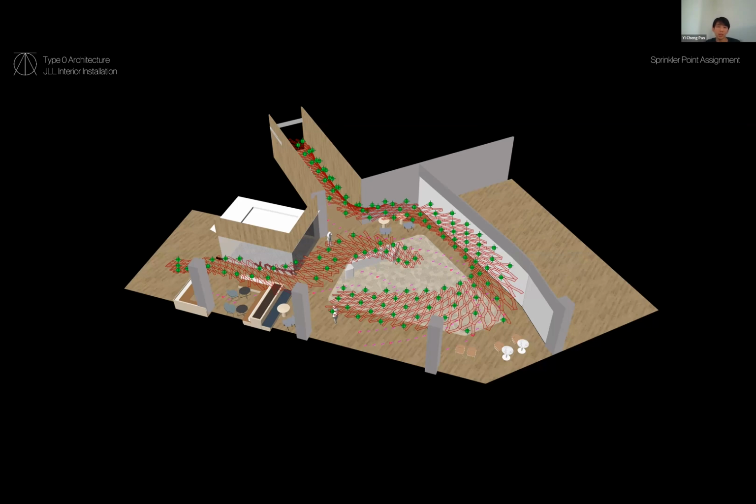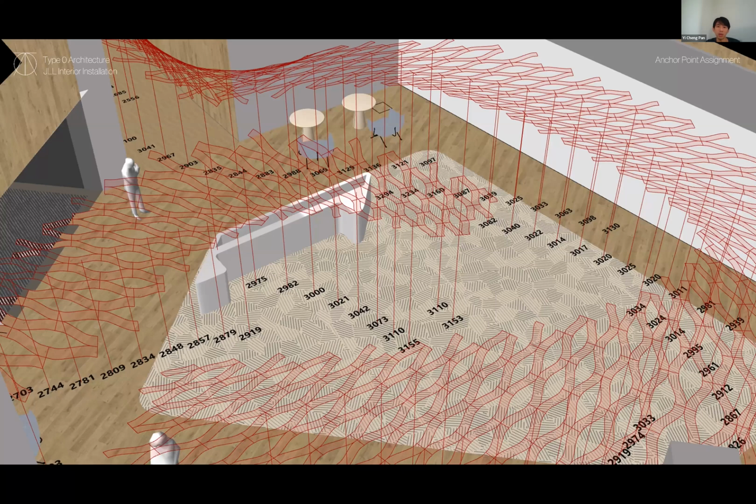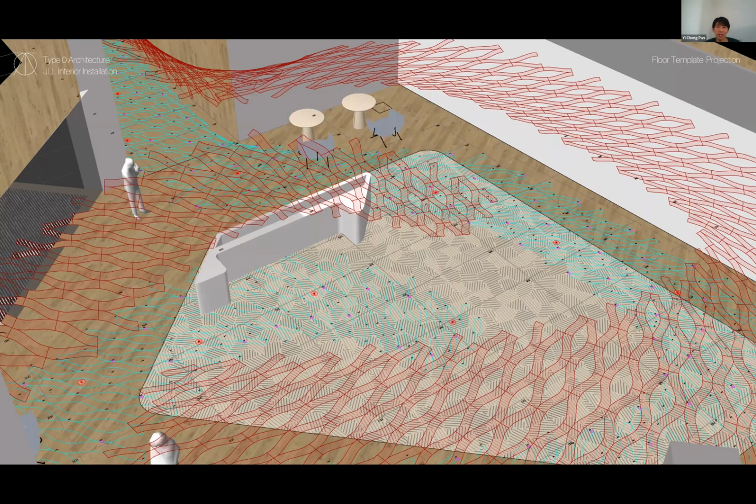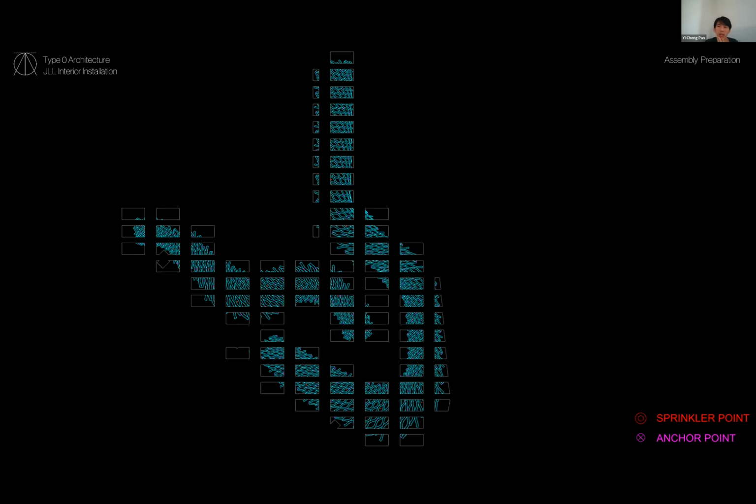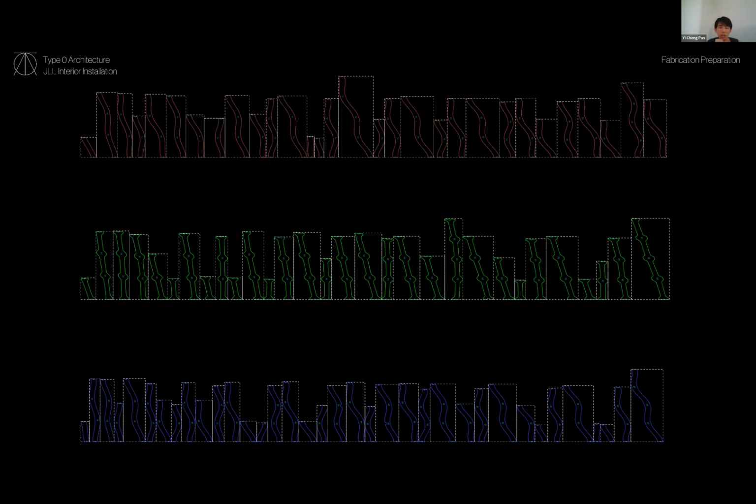And then we also report in our script all the height points that are required to keep the datum aligned throughout the installation. During assembly, this is the templating that we will then lay on site. This helps with coordinating lighting and especially sprinklers. The templating that we lay on the ground marks where the sprinkler needs to be, and the installers will try to match that point.